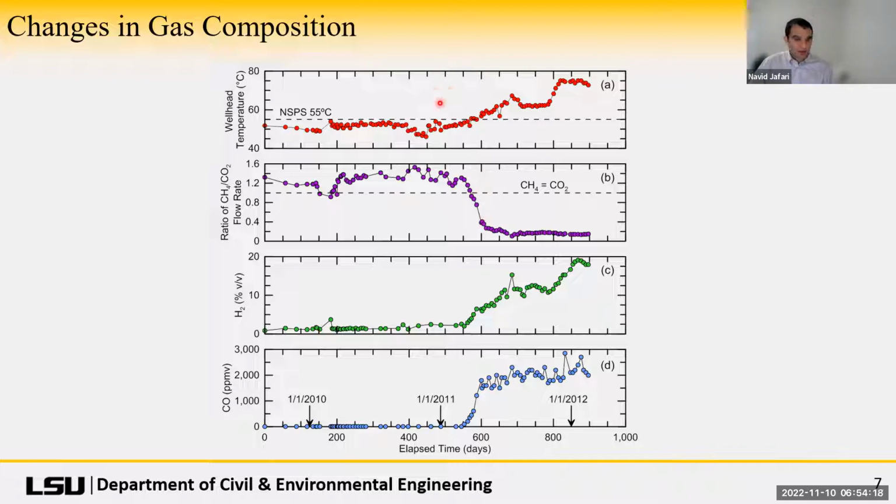So with those two signals, the temperature and flow rate, the other signal that we see correspondingly is hydrogen starting to pick up as the methane starts to decrease. One mechanism for that is the landfill reverting back from methanogenesis to acetogenesis phase. There are other potential reactions, the water gas shift balance could be one.